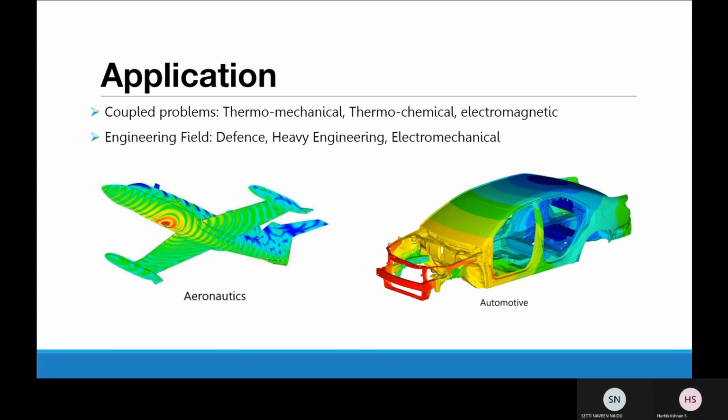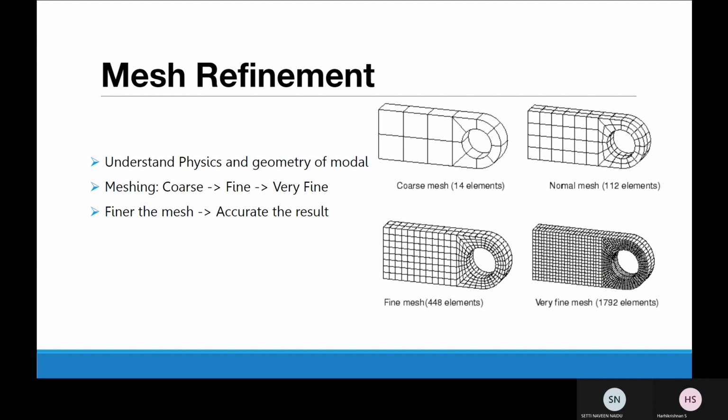In simple words, an analyst should know all the physics that are relevant to the problem, that is the material properties, the loads, the constraints, and any element that can affect the results of interest. These inputs may have uncertainties in them. For instance, the material properties and the loads may not always be precisely known. It is important to keep this in mind during the modeling process, as there is no benefit in trying to resolve a model to greater accuracy than the input data admits.